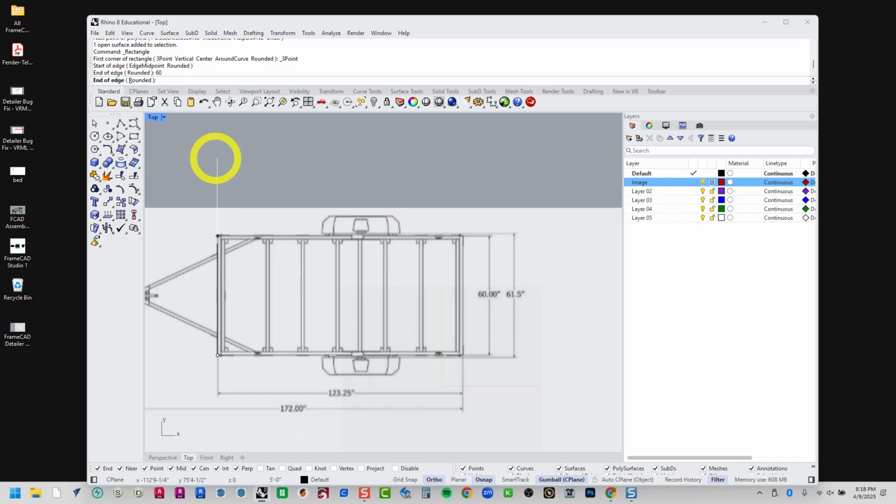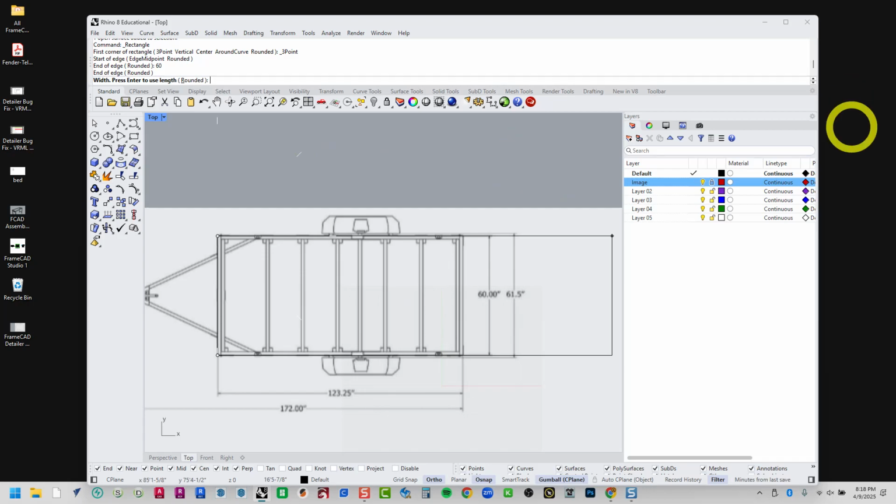And now it's asking for this length, right? If I move my cursor left and right, you can see that line moving. I'm in the default layer, you can see it because I've got default checked. Whenever you have that layer checked and you start to draw things on it, it will take on the color of that layer's color, okay? So even now, if I change it from black and choose magenta, hit OK, you'll see my line turns magenta, and I can see it a little bit better on top of my drawing.